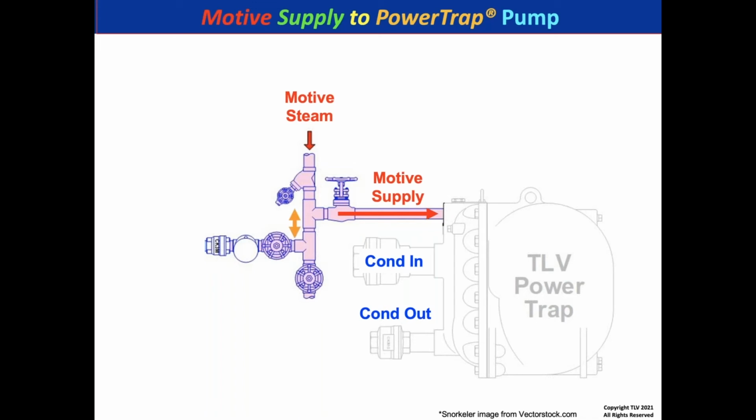That dimension is really critical. Condensate, we don't really want condensate to go up past the trap set on the left. If the condensate goes up into the motive supply, that'll bring debris into the motive valve, and it'll also choke the motive valve, and it will adversely affect performance. So the selection of the motive trap and the check valve after it is quite critical.